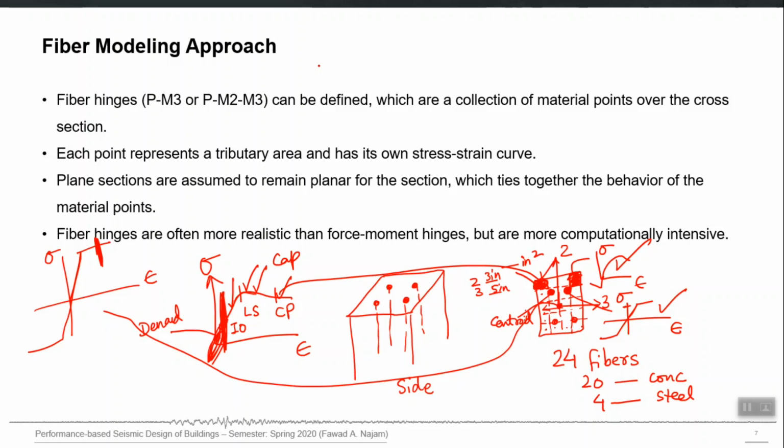If you are modeling a composite section, right, this one, let's say this is your column, it has an embedded I section and some steel rebars also, right? For this kind of a column, ASCE 41 does not provide a, b, c, IO, LS, CP values for composite sections. You may have an irregular section.